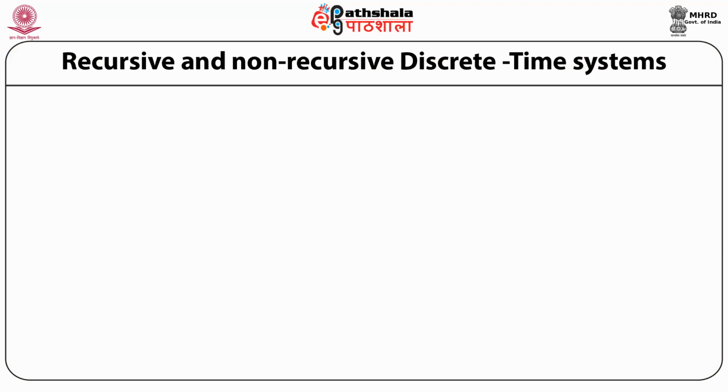We can realize an IIR system using other means, that is by using difference equations, which is practical and computationally efficient. This is very useful for the implementation of digital filters and modeling of physical systems and phenomena.